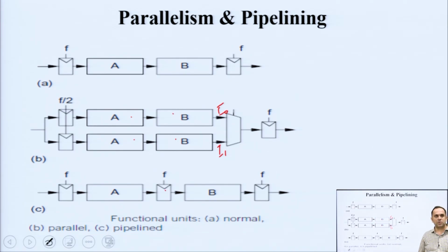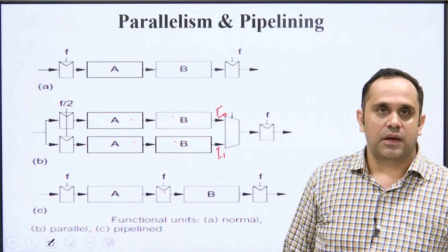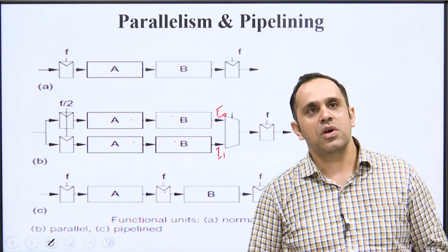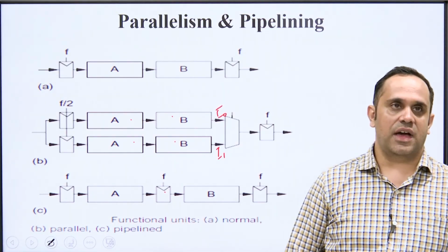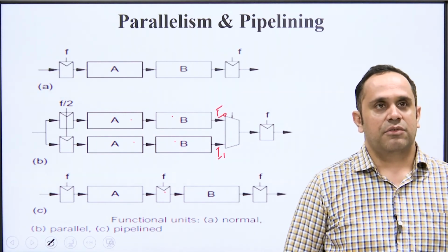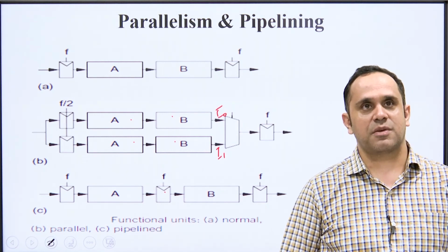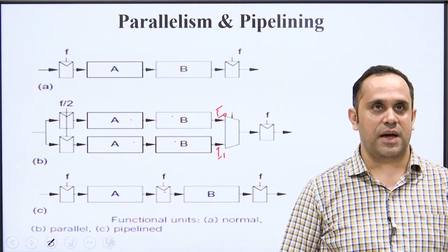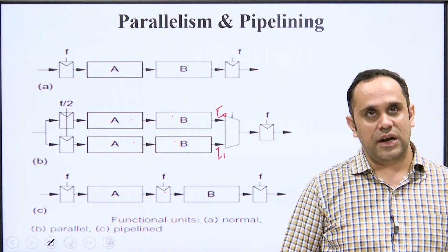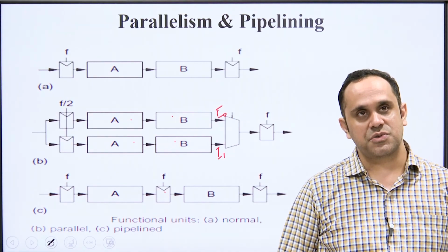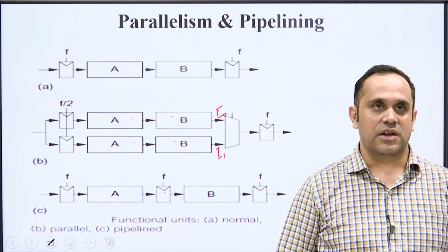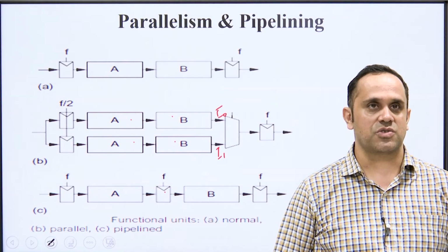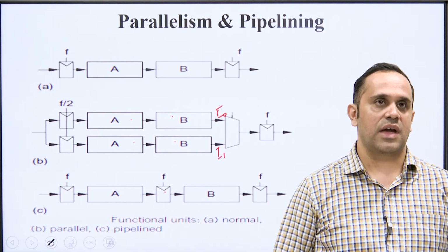These are two more techniques which help you reduce your overall power consumption and produce low power VLSI design. With this we come to the end of today's lecture. We have completed a very important topic where you utilize the effect of power supply voltage on power consumption. There is a quadratic relationship between power supply and power dissipation. When you scale down the power supply, you reduce power consumption, but you increase delays. Increasing delays affect your operating frequency. To counter that, you reduce the threshold voltage, but it increases subthreshold conduction, and to counter that you can use MT CMOS or VT CMOS.